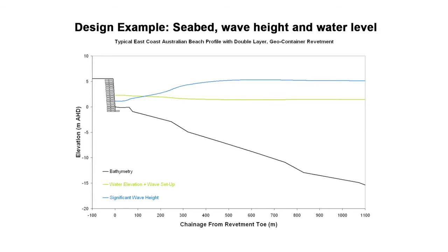The other thing that does happen though, this is our water level, and we might start with about 1.4 metres offshore, but this is where the wave setup process comes in. As the wave loses height, it gives a bit of its energy into the water level, so the water actually rises near shore. That's certainly one of the biggest processes in tropical applications, if you're ever working on tropical atolls, coral atoll type situations, where even though they've got a small tide range, the wave setup brings the water level up over the top of the reef, and then the waves come straight over the top of the reef. So we have a little bit of wave setup in here which brings our water level up quite a bit higher than what we were out in the deep ocean. So that's how we get our wave height at the structure. That's a mid-level way of doing it. There's even more sophisticated ways, but that's a 1D numerical model.